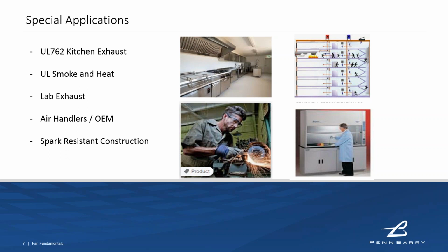Less specific in terms of materials and things like that, but maybe more specific in terms of form factor, is going to be air handlers or OEM equipment. That's usually driven by a very specific space constraint that equipment needs to be in. One of the reasons those stack fans that we talked about, the fan arrays as I called them earlier, were developed was to retrofit into air handlers inside of large old buildings. So imagine that you have an air handler on the 50th story of a high-rise building.